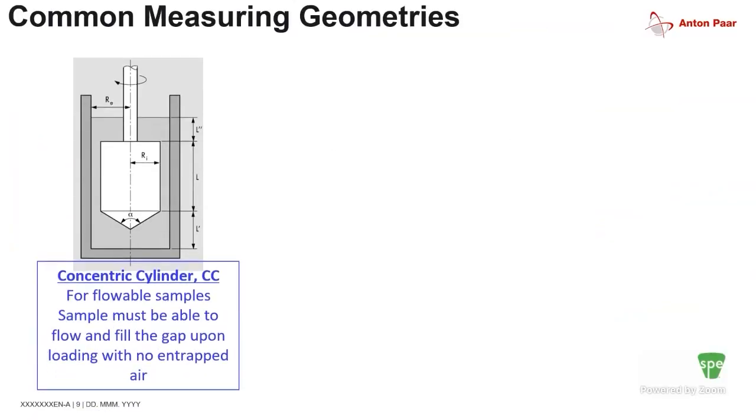And so likewise with rheological or viscosity or modular behavior, there are different types of geometries that can be used. For low viscosity, low molecular weight fluids, I can use what's called a concentric cylinder. So again, for easily flowable material, things on the order of, say, 100 to 1,000 centipoise or lower, that I can actually fill into this bob and ensure that I can get into there.